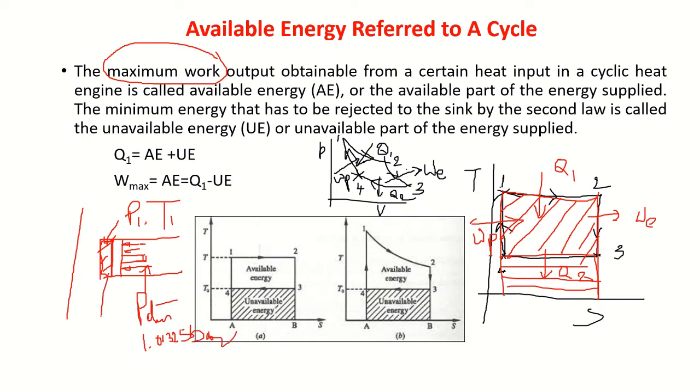And let us say this pressure is something like 10 bar. So this is 10 bar, this is 1.01325 bar. Because of this pressure difference, the piston will start moving towards the right. It goes on moving till the pressure on either side of the piston becomes the same, 1 atmosphere. Correct?